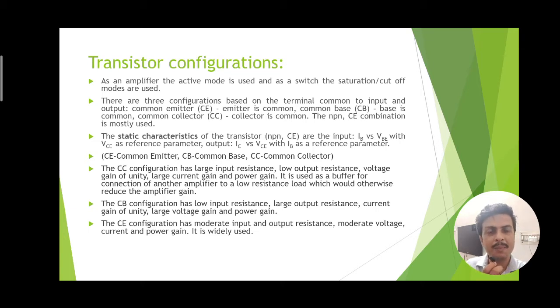Similarly, for the common base configuration, base is common to the input and output section, in which emitter plays the input terminal role and collector plays the output terminal role. In case of common collector, base is the input terminal and the emitter is the output terminal. So in this way, the three configurations are used depending on various types of requirement, such as the input